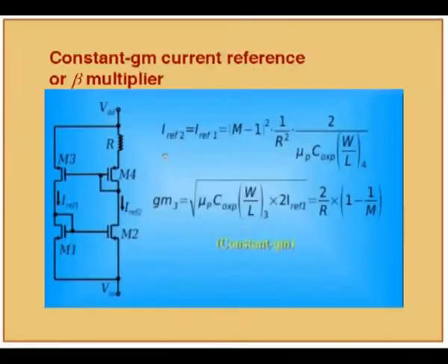Even if it is off chip, because of temperature it may change, yeah, but I agree. Ideally always everything changes, but the amount of change you observe in a discrete resistor is much less than in an on-chip one, because an off-chip resistor sees ambient temperature, but on-chip resistors sense chip temperature.